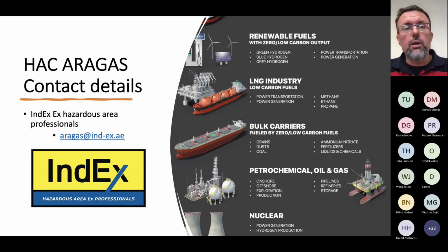How you do the hazardous area classification is your topic, but you have to have one, and you have to have a valid one. This validation is related to the technology, functionality, applied explosion protection methodologies, and time as well. You need to define all this in your Site EX policy, as we used to say, and it shall work accordingly.